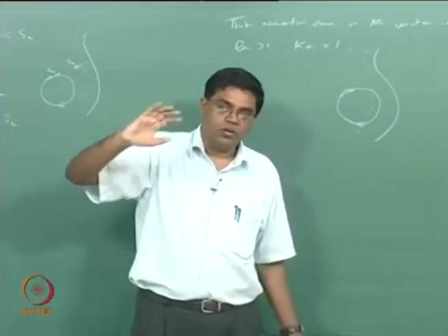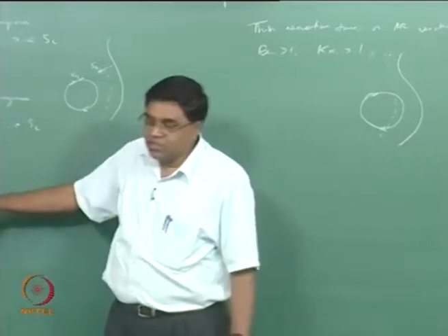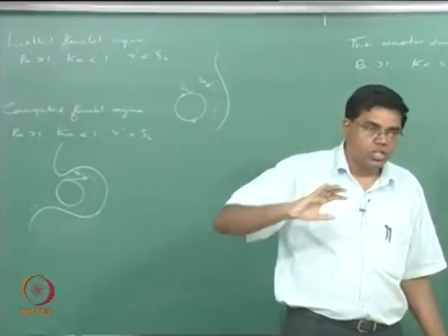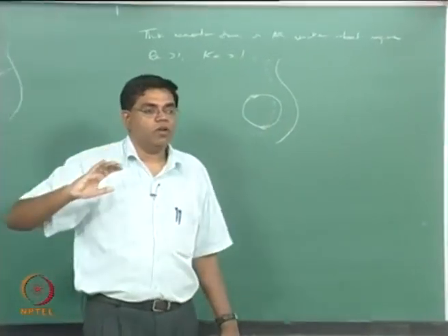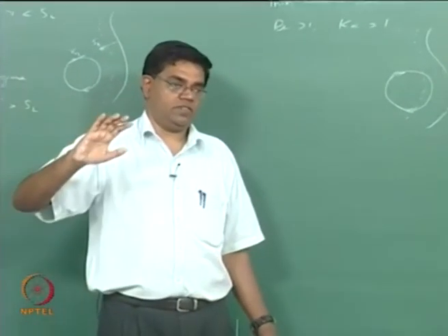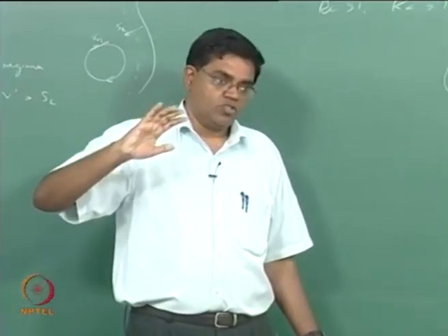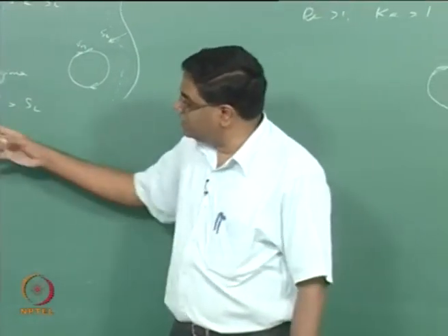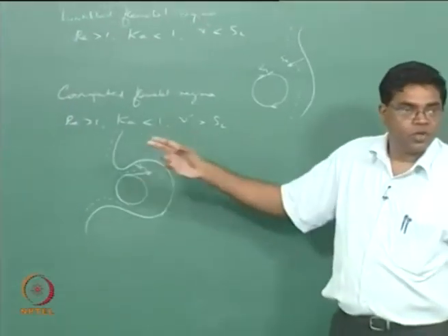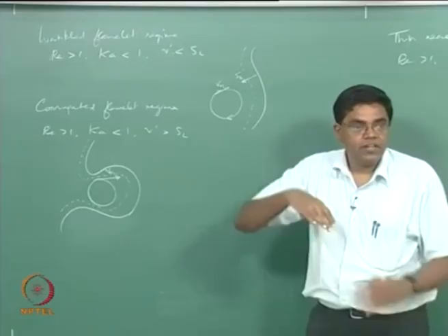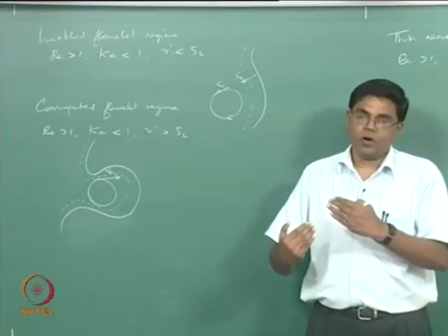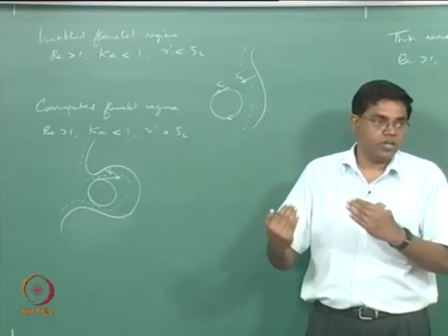That means in these regimes we can still continue to think about the turbulent flame or the turbulent combustion zone as being made of an ensemble of laminar flamelets, right. So locally where you have these things satisfied, you can now say it's essentially a laminar flame, but it's now interacting with an eddy and therefore it's getting curved or corrugated, wrinkled or corrugated, right.